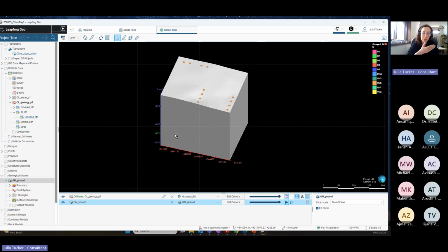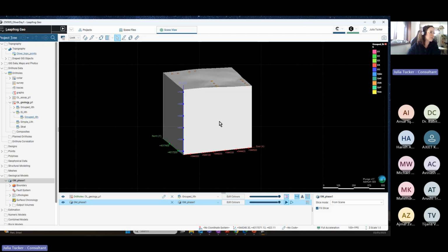I wanted to get here because this way you can visualize what we are trying to get. Why? Because you are seeing the dikes, you are seeing what I'm trying to group or to split, but you may not be understanding why I am doing that. I am doing that because the geological model is a block. So why I have told that the 3 most important things right here are the resolution, the boundary box, and the trends. Why?